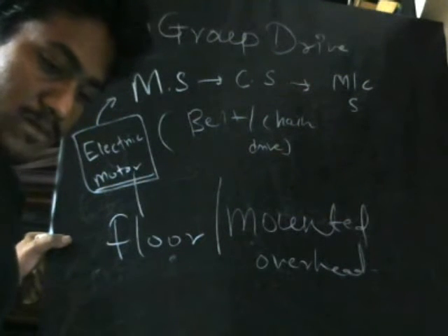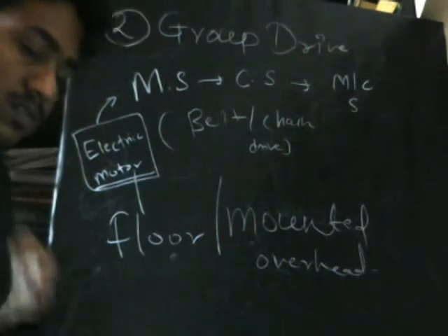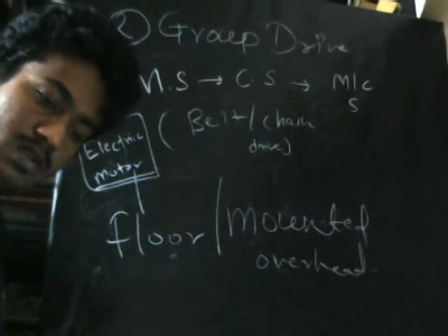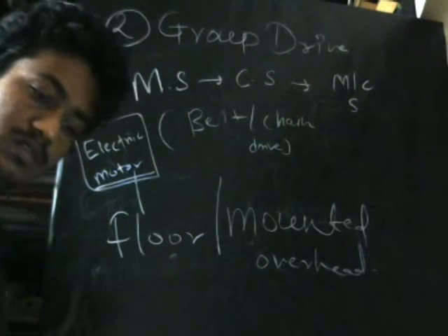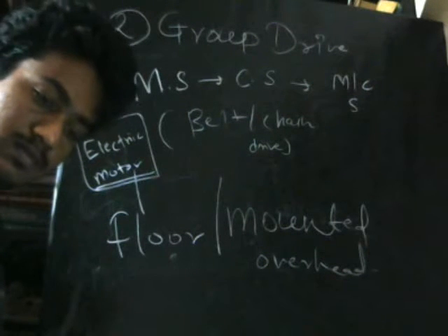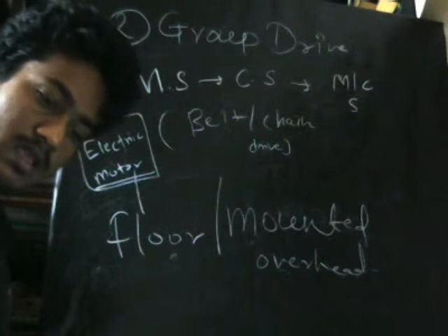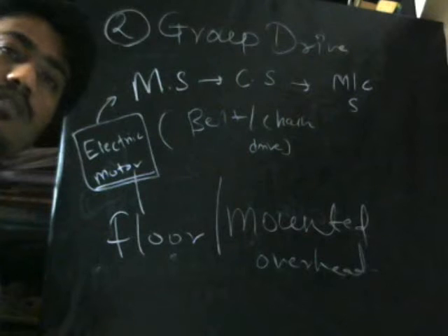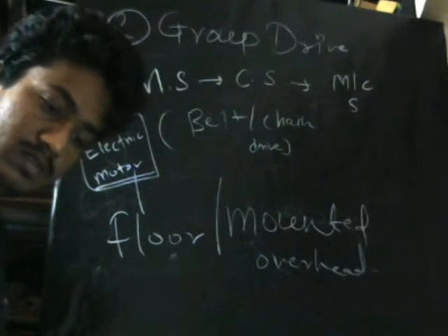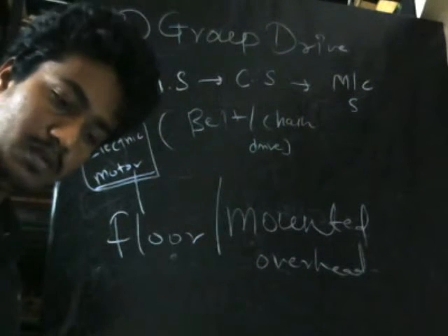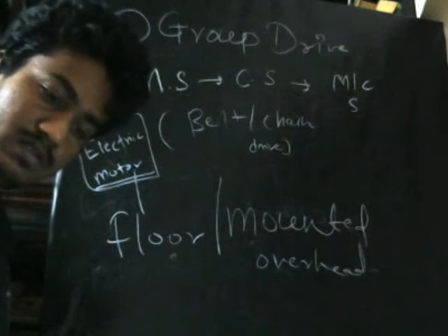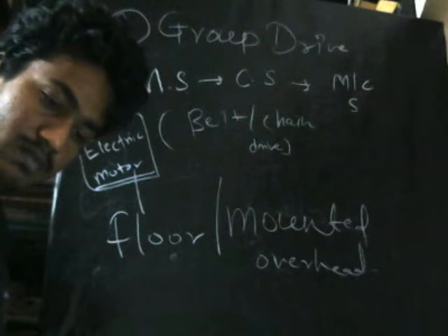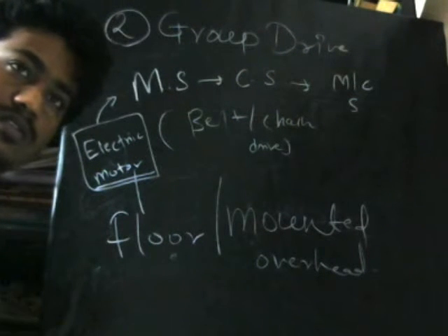So now next point is group drive is suitable. Where is it suitable? Where power consumption of individual machine is extremely variable, and with occasional brief high peaks. So this is more economical in fixed charges, power consumption, and maintenance. But group drive has the following disadvantages.